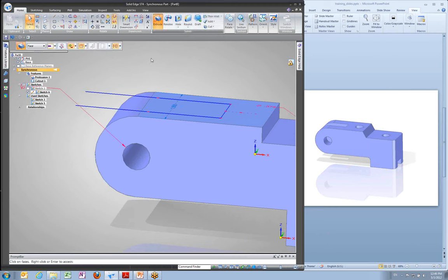What we have is the Extrude command. If we click that, by default it wants us to select a face to extrude. I'm going to change that to chain. And all a chain means is a sketch that's continuous. So you'll see now we can select that whole edge there that we drew. The next thing we want to do is make sure that we're actually removing material and not adding material because we're cutting it away.